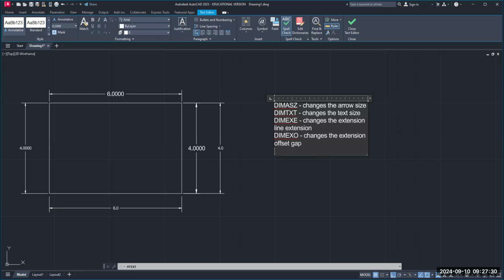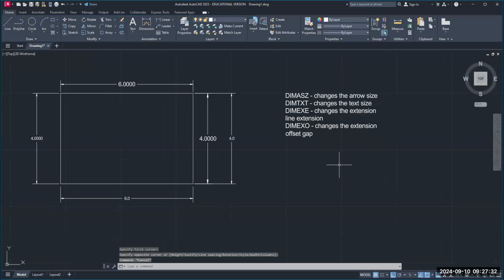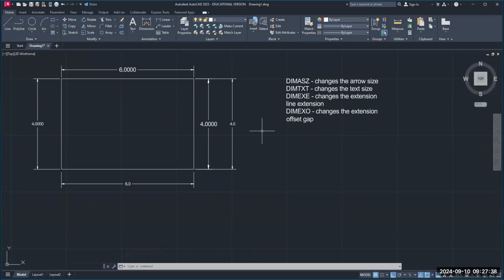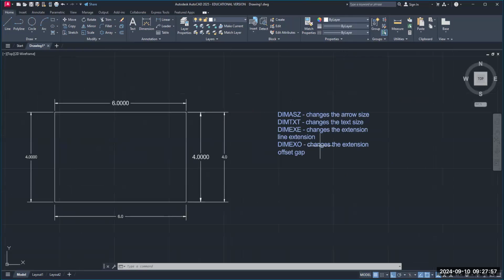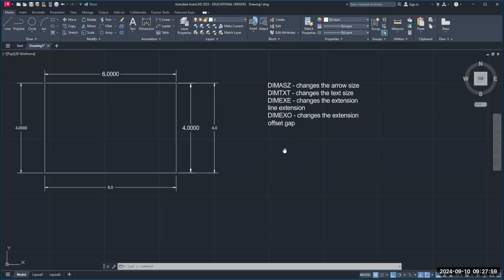Hit enter and then click anywhere on this. So I put some text here. You can play with the text. It's just like typing text anywhere else. But I do want to tell you this. I have lowercase letters there, but you don't use lowercase letters on a drawing. They're always uppercase letters. Okay, all your letters on a drawing, uppercase. I did this because I was creating some definitions here, kind of like writing notes.